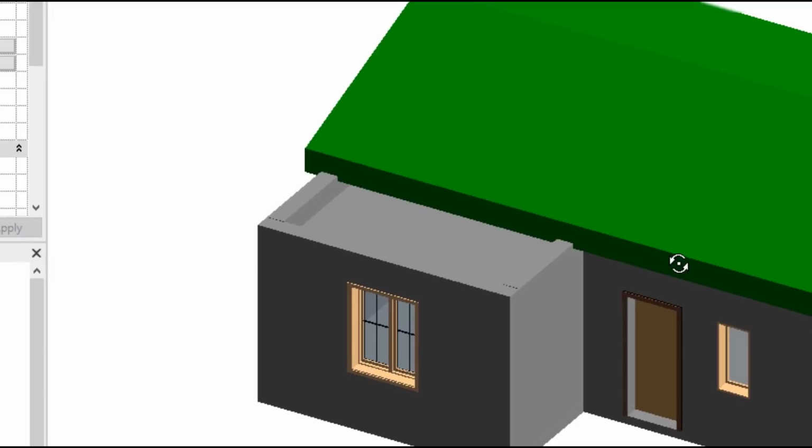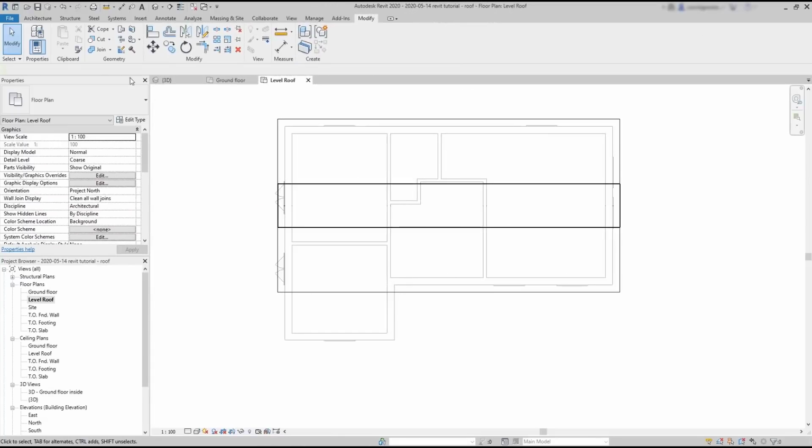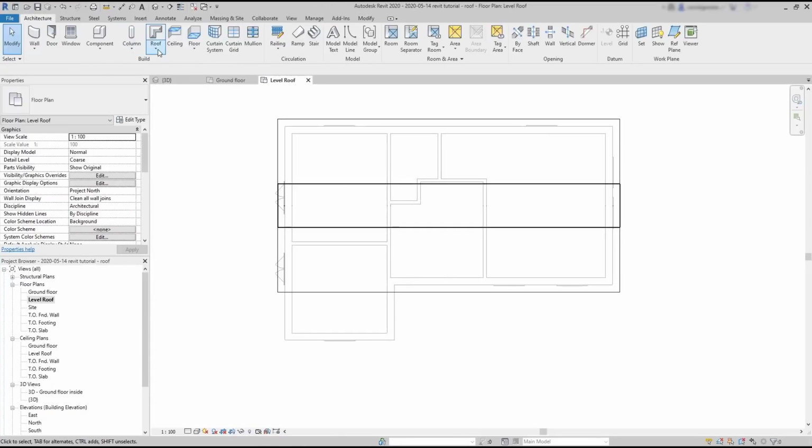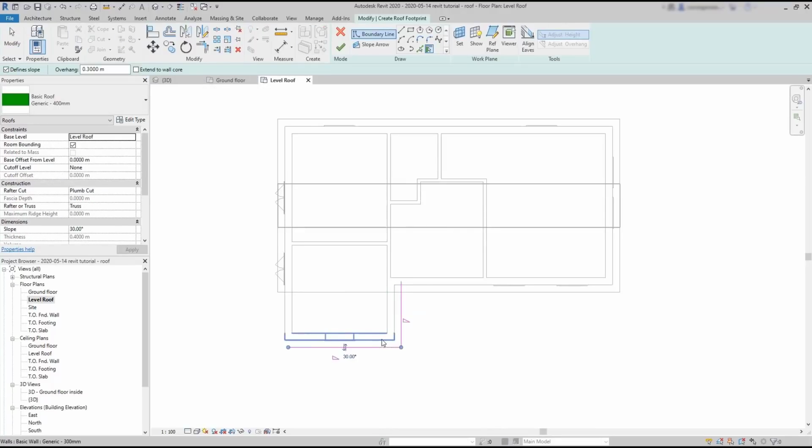So let's go again to the roof plan. I activate again Roof by Footprint. Click on these 3 walls. Then I need to switch to Draw a Line. I click on this endpoint and draw it up to this intersection. And to remove the extra part, one of the possible ways is using Trim. Select this one as the reference line, then click on the part of the line to trim that I want to erase, which is this side.